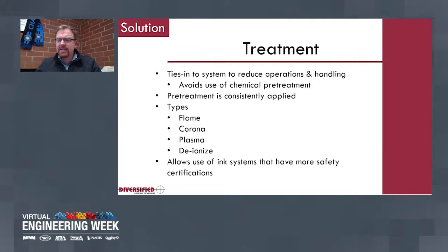So anytime we have a customer with a project that needs pre-treating, we really encourage using that in the automation cell. Yes, it does drive up the cost, but not having a treated part in the field can be an absolute failure. A lot of times you see people using the chemical pre-wipes instead of Corona treat or flame treating, and that's just not exactly the safest anymore in our operations realm of safety that we try to work with. So we want to try and stay with flame and Corona treat and plasma treat.